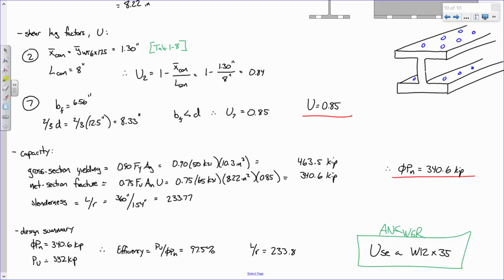There's an abutment right here, and an abutment right here. What we typically do in bridges is we have one bearing that's called a fixed bearing and one that's called an expansion bearing. A simple way of thinking about that is we might use circular holes here to bolt that down, but we might use a slotted hole here.